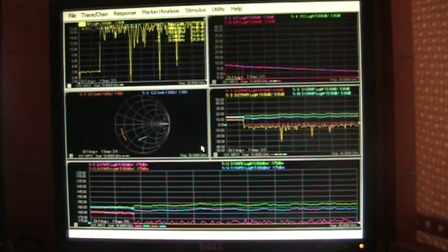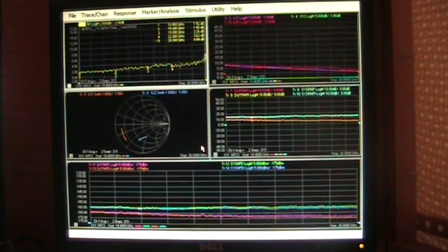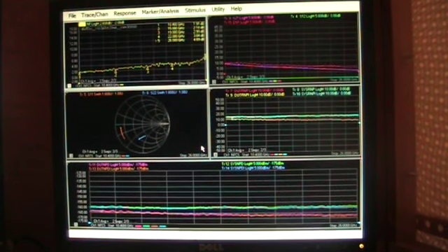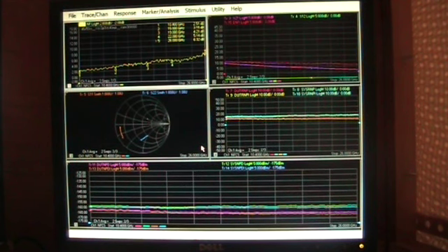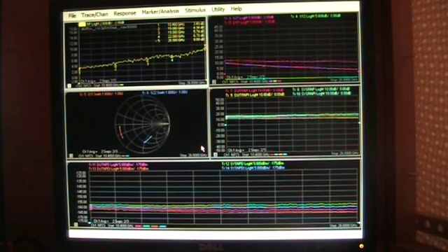The proper de-embed file will be applied. And again, the first thing we do is we measure with the tuner in the initialized position. As you see, as you go up and up in frequency, the reflection coefficient presented to the DUT in this initialized position is not as clean as before. It's not as much the effect of the tuner as it is the effect of the entire apparatus. This is measured at 4 points, and then the tuner will move to a new position. The corresponding de-embed file will be dropped in again, and then we'll see the noise figure.